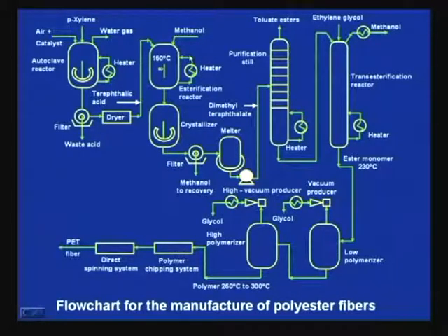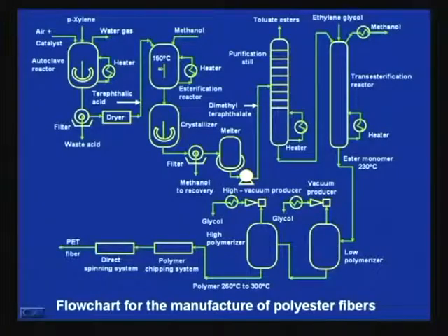Otherwise, what will happen if your company buys DMT from outside, then methanol will be a byproduct in your unit, then that byproduct is to be sold, otherwise cost competition cannot be reached. So, it is for those reasons it is better to manufacture DMT in the same installation.